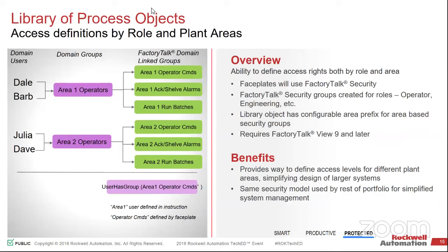Now what you can do is that same user level can be tied in through the groups. So I can now nest all of this operation, put groups around it. Keep wanting to do a pointer. There we go. So now you can go in there and tie in the security that you would normally have as part of your administrative groups, your engineering groups, and your operator groups, and pass that all the way through your HMI system. You can still use the A through P codes, but you can now use this for a lot better granularity.